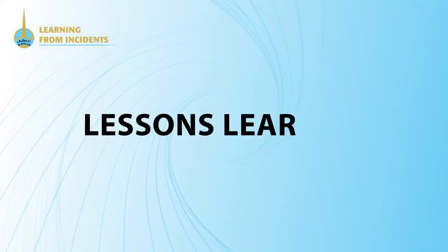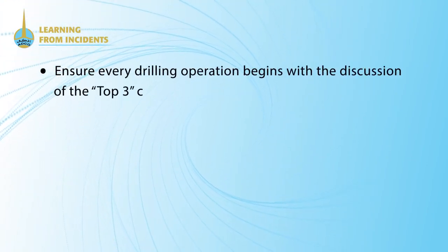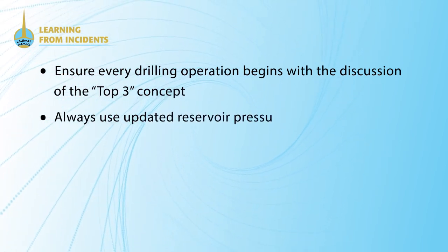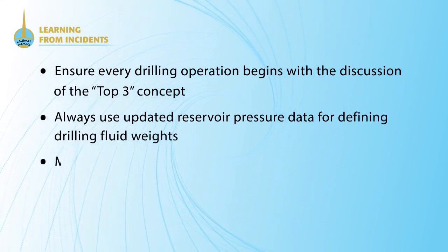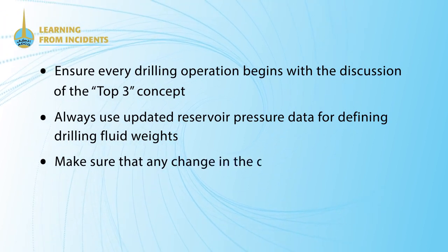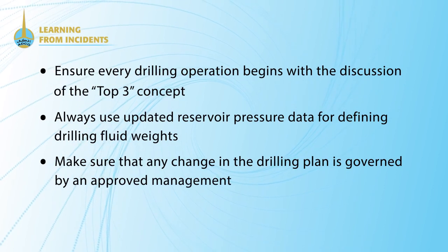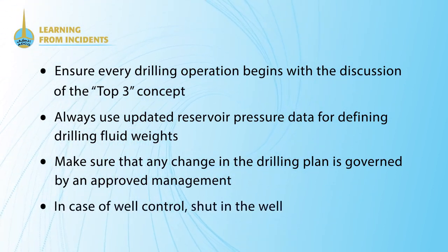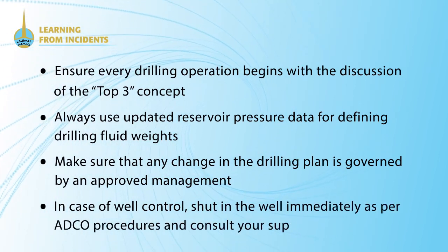Learning outcomes from such incidents include: ensure every drilling operation begins with the discussion of the top 3 concept. Always use updated reservoir pressure data for defining drilling fluid weights. Make sure that any change in the drilling plan is governed by an approved management of change process. In case of well control, shut in the well immediately as per ADCO procedures and consult your supervisor.